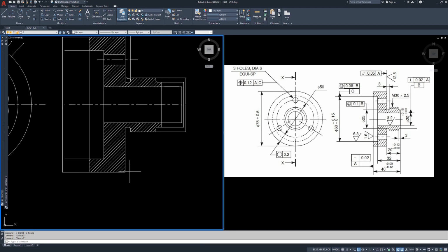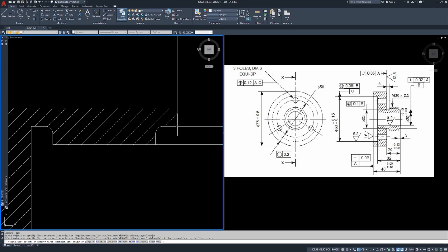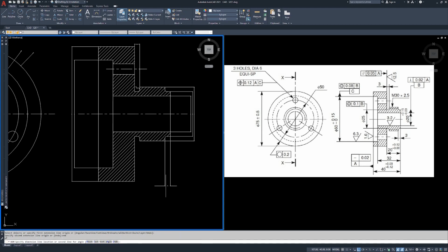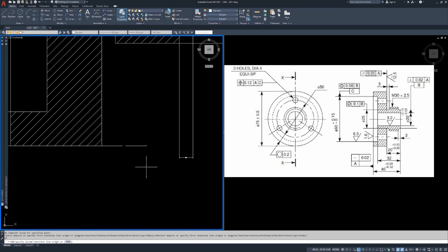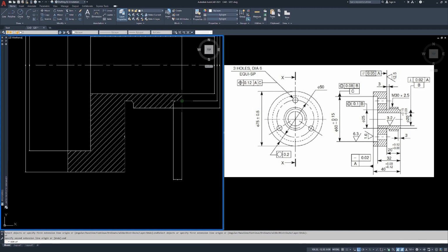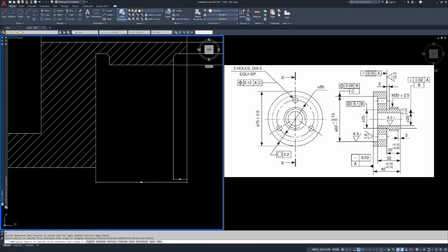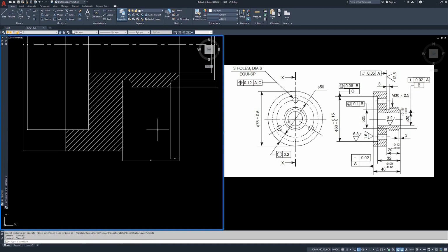Let's get our horizontal dimensions in here. Type dim. Let's get our 3 from here to here. Pull it straight down. I like to pull dimensions down beyond the edge of the actual part itself. END again. What are we looking for? Our 20. Pull that to there. Ooh, I lost that endpoint. Pull that straight down. That should be 20. It is. Then we need our 32.